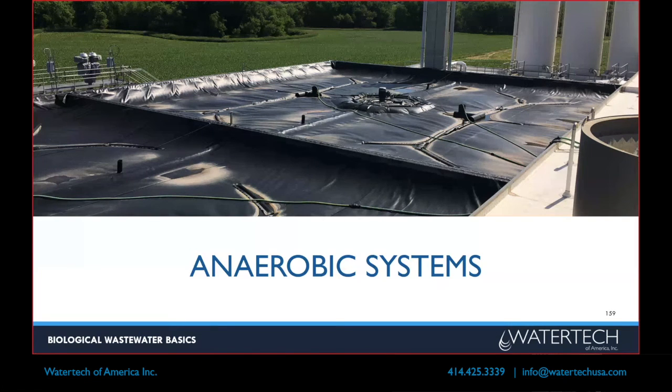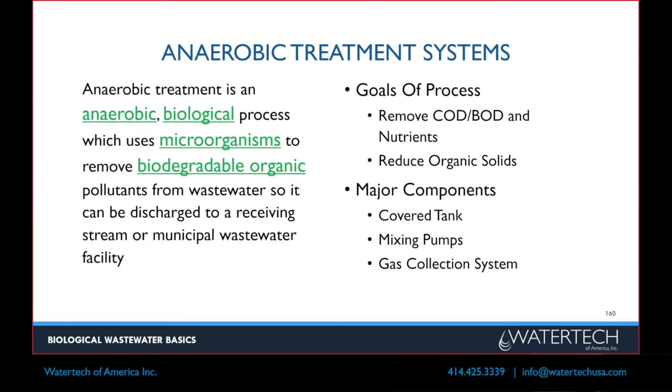So it's covered, and you have to maintain temperature and mixing, and then it'll generate methane, with gas recovery piping around the perimeter that will take the methane out, and then you have to decide what you're going to do with the methane. Again, it's an anaerobic biological process which uses microorganisms to biodegrade organic pollutants.